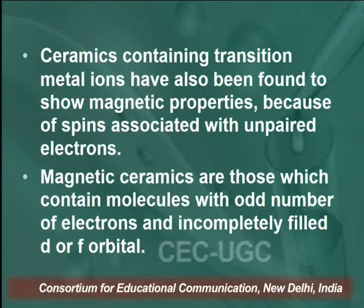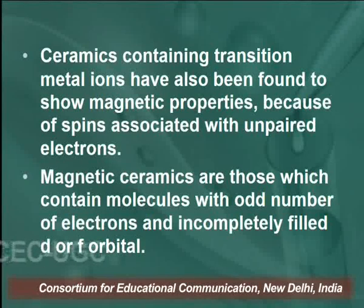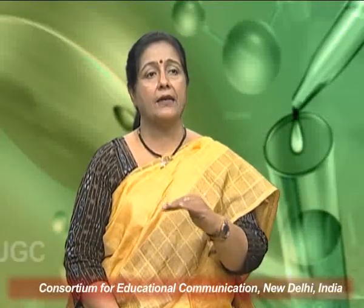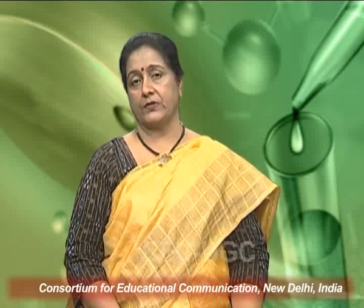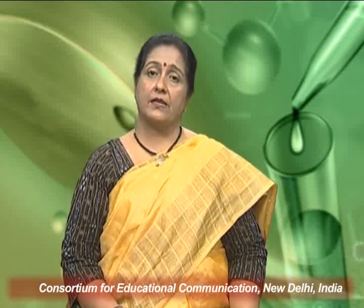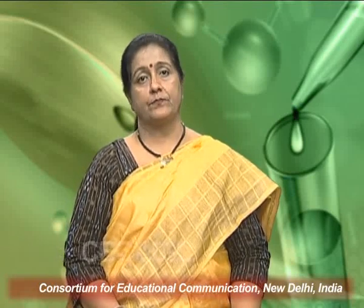Magnetic ceramics are those which contain molecules with an odd number of electrons and incompletely filled d or f orbitals. Unlike magnetic metals, magnetic ceramics are bad conductors of electricity and hence do not conduct electricity. Magnetic ceramics respond to a magnetic field, known as magnetic susceptibility.